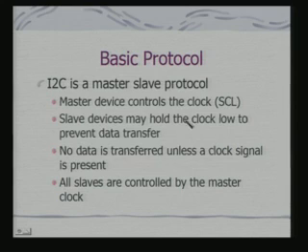The basic protocol is a master slave protocol. In fact, there is no external clock generator. There is a master device, the current master. In fact, master and slave can be interchangeable. The current master can become a slave for another application. So, the master device controls the clock. The slave devices may hold the clock low to prevent data transfer. So, the master is driving the clock.